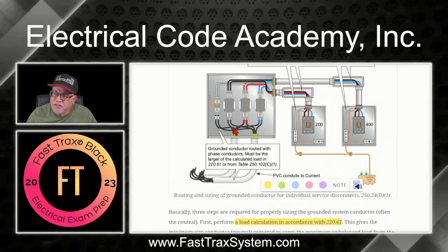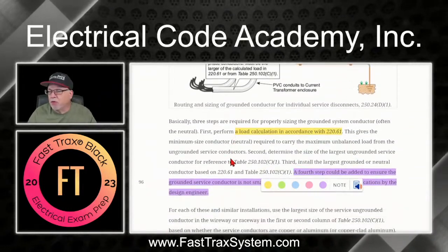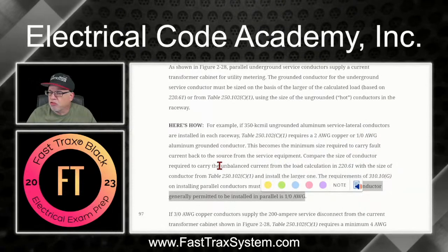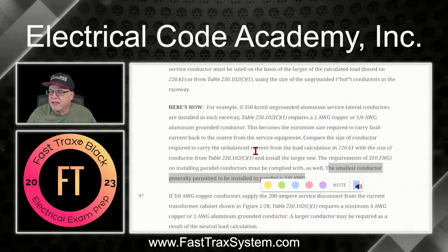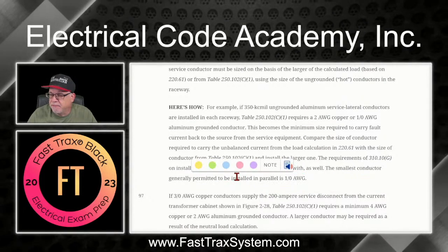So we had the minimum size that's required for these raceways, but we also have to remember that if it's applications being installed in parallel, that it cannot be smaller than 1/0. Okay? Remember those paralleling rules. All right, so don't simply stop and think that, okay, that's a minimum size and we're done. Again, always remember we have paralleling rules that have to be met.